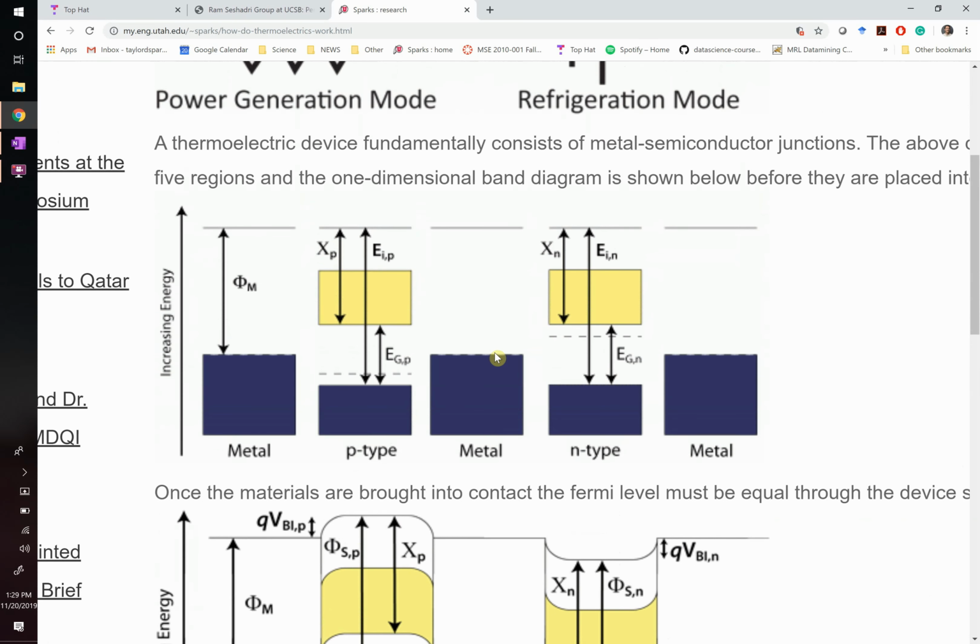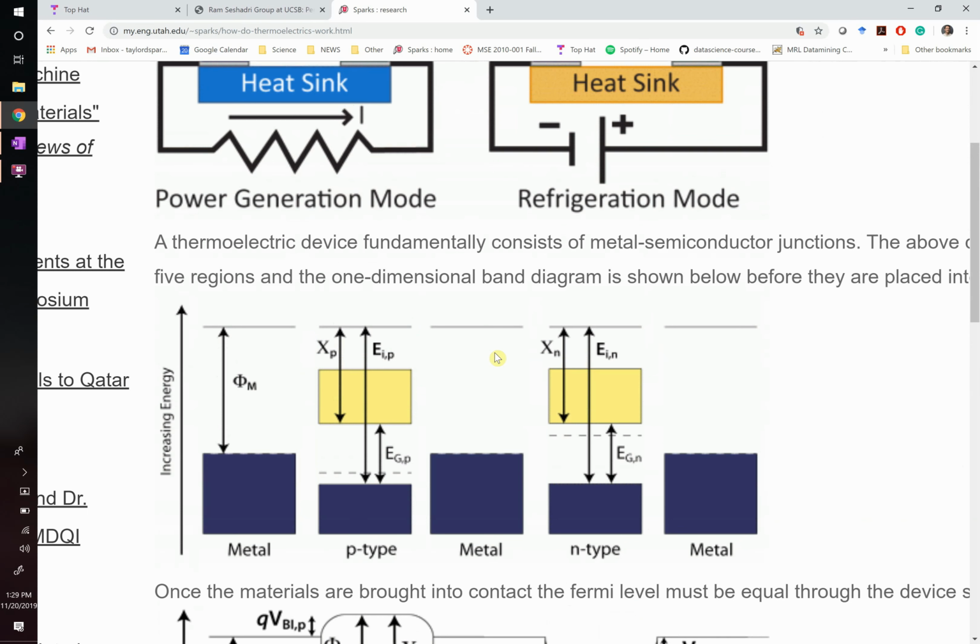We have to consider a bunch of band diagrams. So here's a P-type material. Notice I've drawn this dotted line for our P-type material. These represent the acceptors that you can jump up to and fill the spot, because you've put acceptor ions there. Excuse me, acceptors, not donors. Here in the N-type, you put donors like phosphorus that can easily ionize.